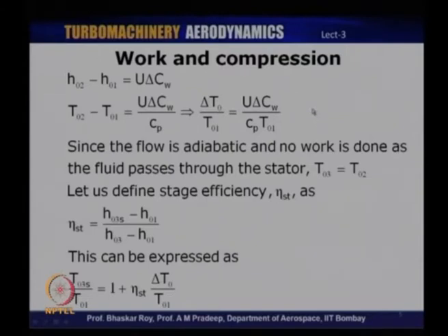Now, since the flow is adiabatic, as that is one of the basic things that we have seen in the last class, there is no work done as the flow passes through the stator, and therefore, T03 should be equal to T02.